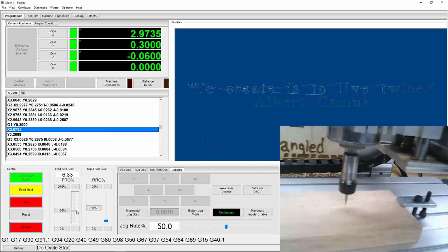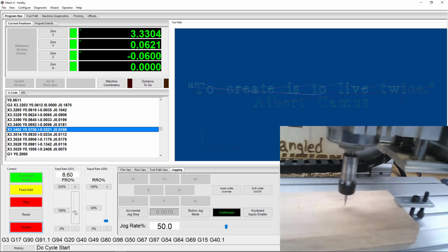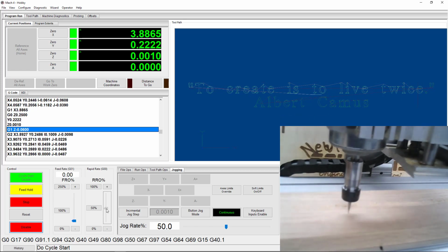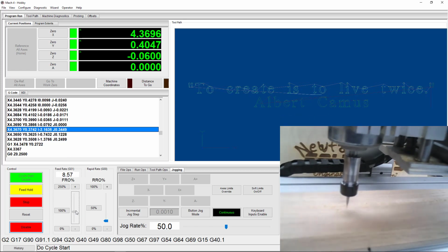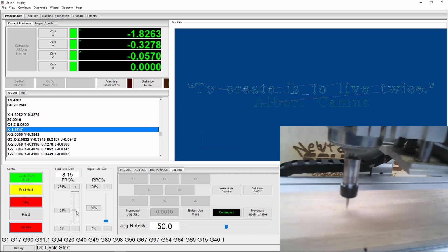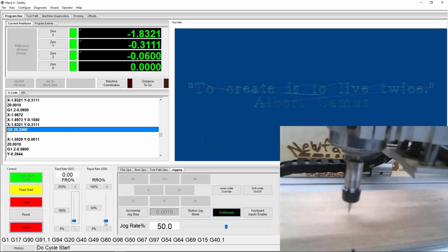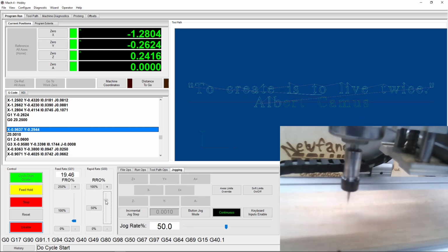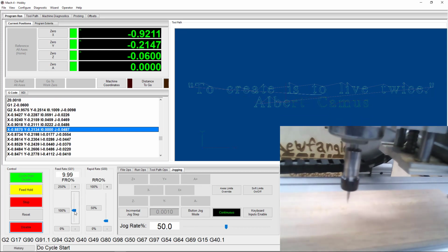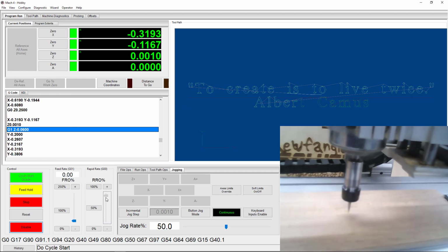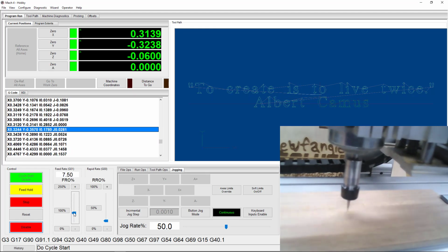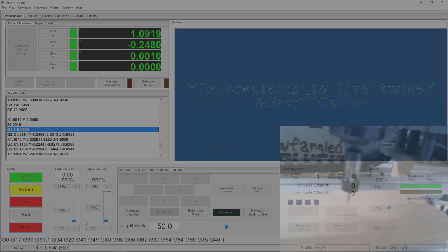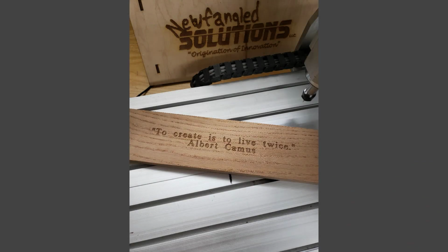Make sure all safety measures are in place before you begin cutting. Always load your G-code file from your computer directly. Once your G-code is loaded, jog around to help sync up the toolpath on your screen with the material on your table. Use a work shift to do a dry run of your cut. Move the feed rate and rapid rate sliders up one at a time to control every move. Watch for the 3 times you're most likely to crash: at the beginning of the cut, during any tool changes, and at the end of the cut.